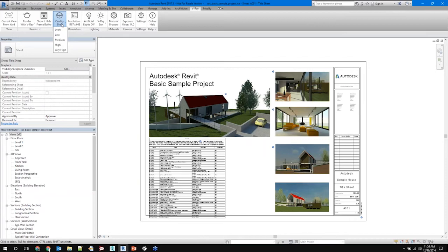Quality levels, it's good to do low resolution draft renders while you're trying to set up your image. And I typically suggest that people do a model in white rendering, which I'll show you here in just a moment, to get their lighting right. And once the lighting is right and they're happy with the overall lighting, then they can work on tweaking individual materials by turning off the override materials and focusing on each of the individual settings.